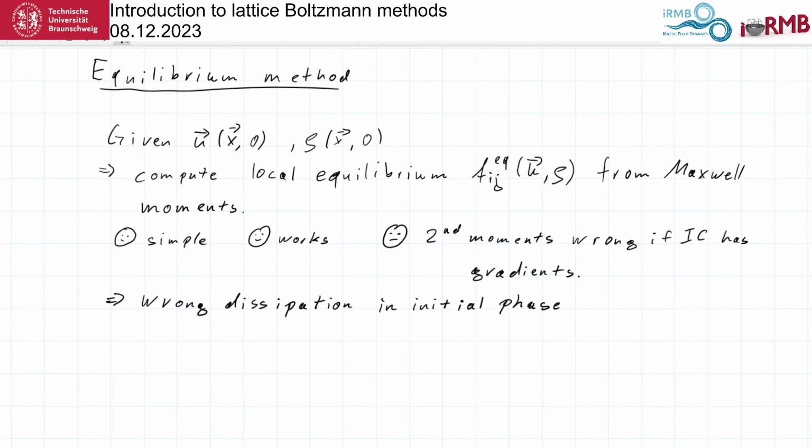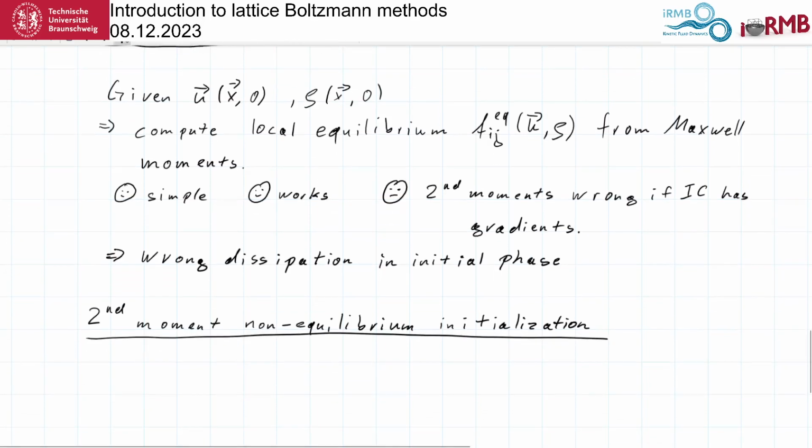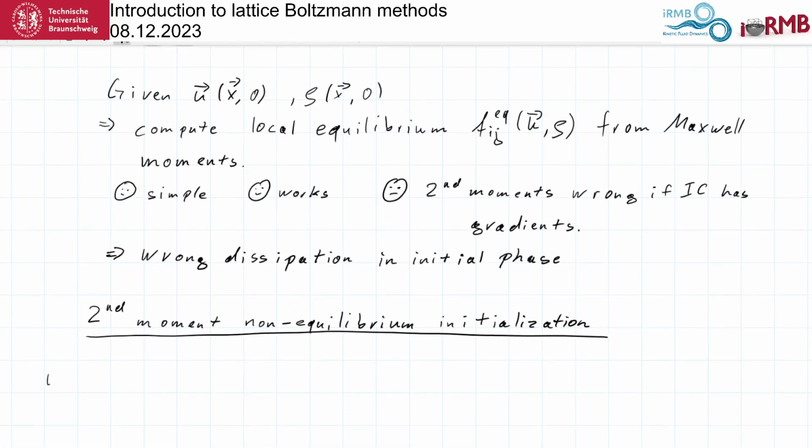So let's see, what would you do if you are interested in accurate initial conditions. So then you will have to set a second moment non-equilibrium initialization. And this second order non-equilibrium initialization makes use of asymptotic analysis.